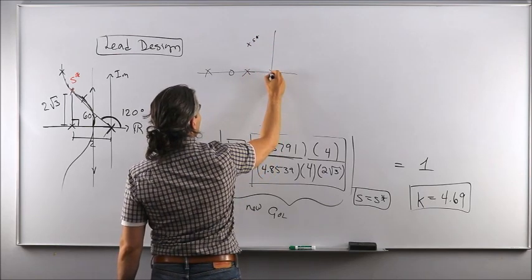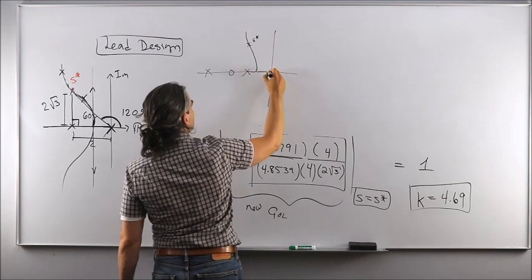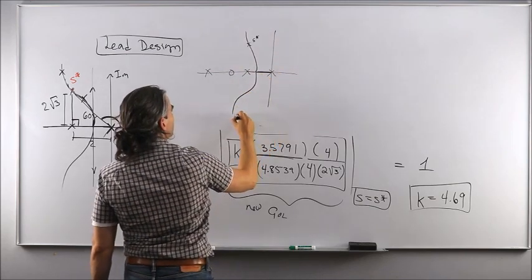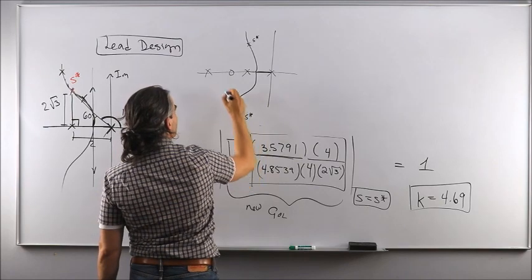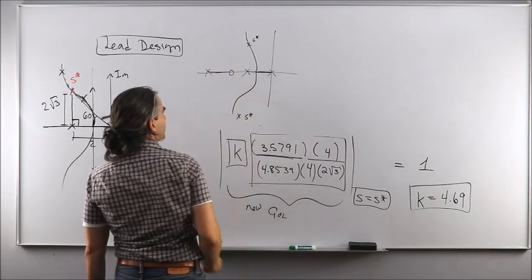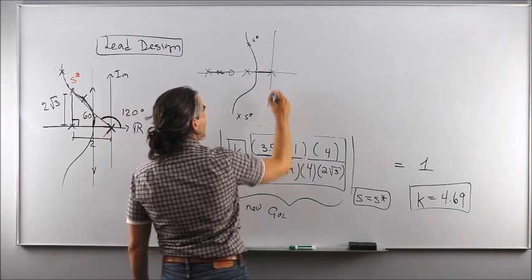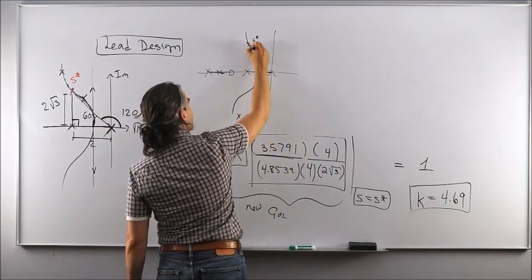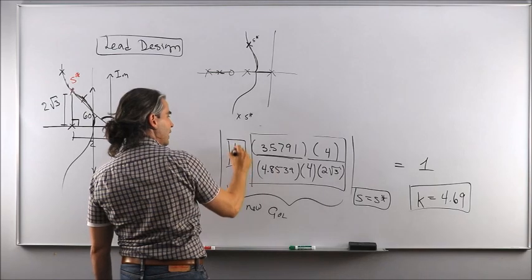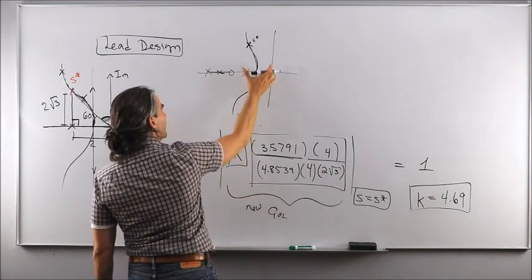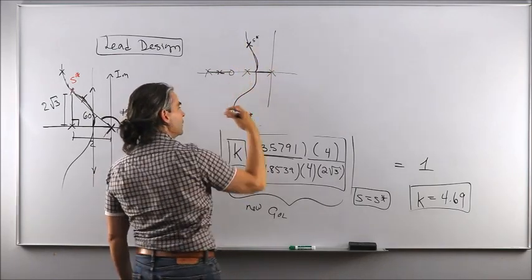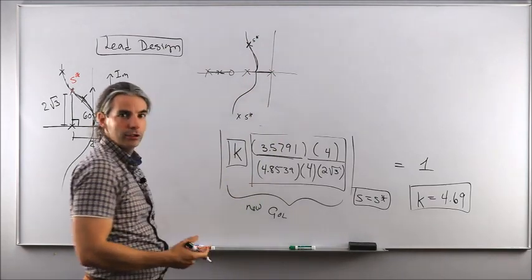So those two would probably do something like that. Boom. Another S star down here, and those two, something like this. I don't know. But what is important is that you've stopped your poles directly at S star by carefully gauging the gain here, and that you've bent the branches to go through S star through the phase condition we saw earlier.